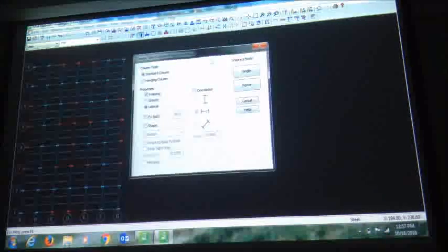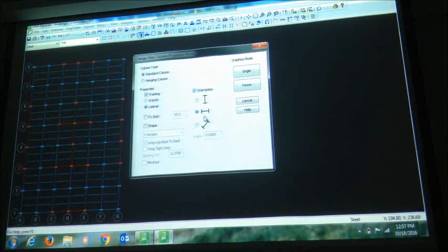Now look at these beams and columns. They are bending about their strong axis, but these ones, are they bending about their strong axis? They are bending about their weak axis, right? Are you following me? These columns are bending this way, which means they are bending about their weak axis. So I need to change the orientation of these columns also. Go columns, change properties, and the only thing I need to do is change the orientation. Instead of this one, click this one, fence.